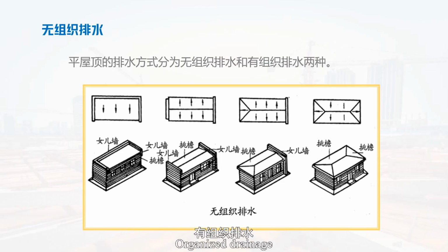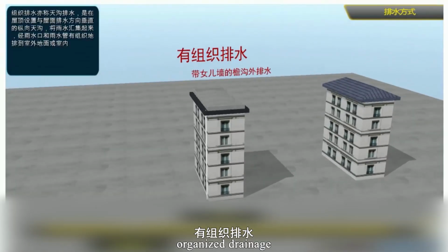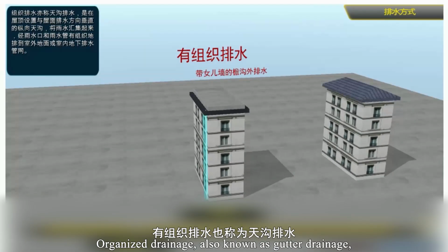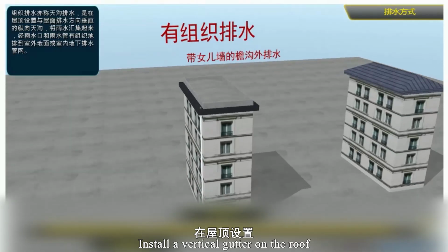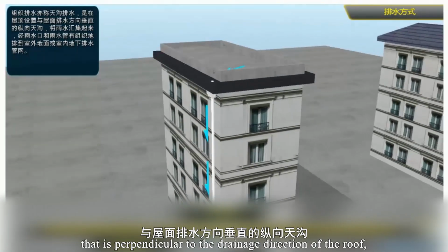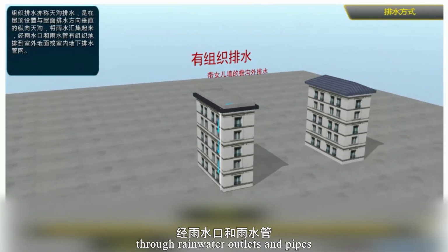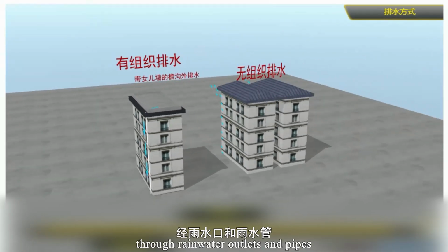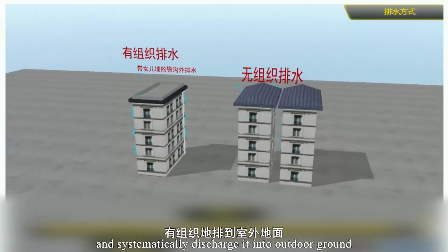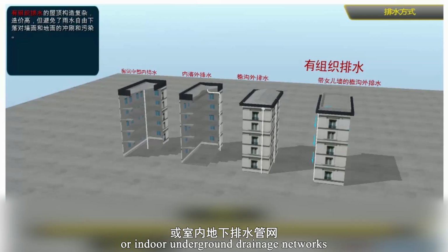Organized drainage. Let's learn about the second type of drainage, organized drainage, also known as gutter drainage. Install a gutter on the roof that is perpendicular to the drainage direction of the roof. Collect rainwater through rainwater outlets and pipes, and systematically discharge it into the outdoor ground or indoor underground drainage networks.